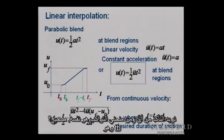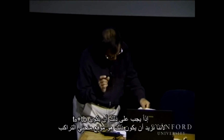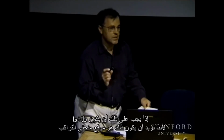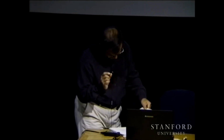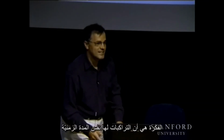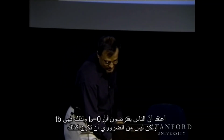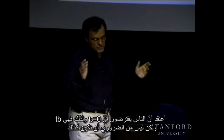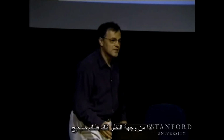We want to make sure that the time of the blend is the same, right, which is T sub B. So that should really be T sub 0 plus T sub B, because you want that to be the location of the blend. Okay, let me move over that. I can't resolve it right now, but it makes sense. The idea is that the blends have the same amount of time, right? I guess people are assuming that T sub 0 is 0, and that's why it's T sub B, but it doesn't have to be. So from that point of view, that's right.